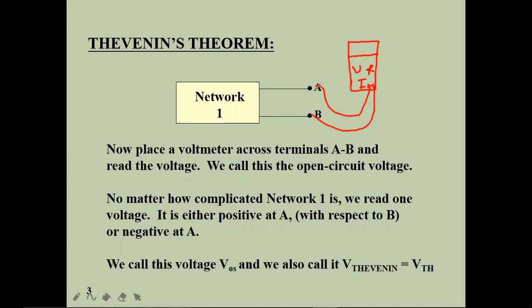By connecting them directly, you can measure the voltage over here. You may have some voltage across network 1, that is called Thevenin's voltage, VTH. So you can measure voltage directly by using the DMM. This is one practical way of measuring the voltage. But in the theoretical way, you should measure the voltage across A and B by a procedure.